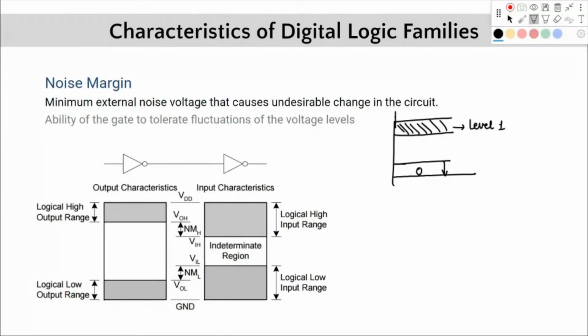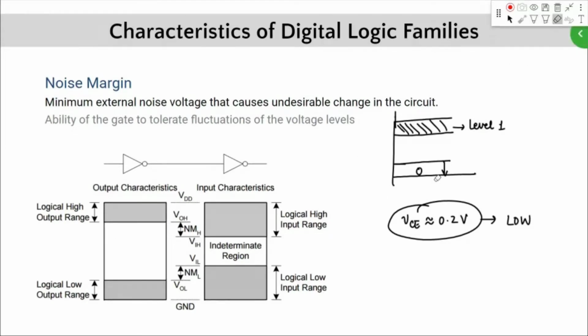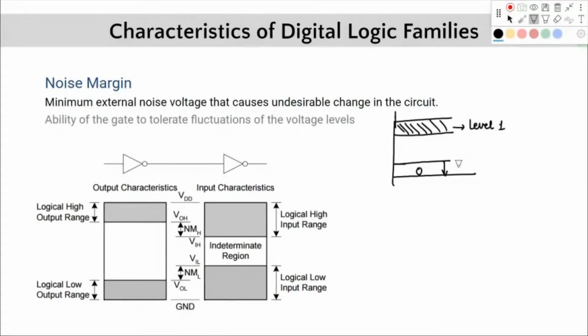You already know, think of when you studied BJTs. What did you study then? You studied that in saturation mode the value of VCE is around 0.2 volt or even less. So what did we overall call it? Yes, this is a low level. It was not exactly equal to 0, right? This is how in practical application there cannot be just one hard threshold where you say okay, this voltage is high, this voltage is low. No, you have to define a range.